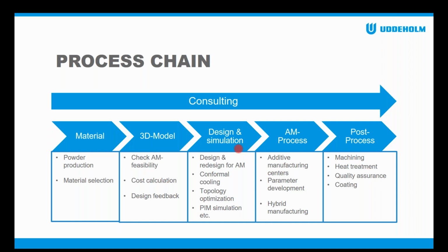Well, often when you turn to additive manufacturing for plastic injection molding, it's because you want to maybe decrease the cycle time or improve the quality of the produced plastic part. And you do that by improving the cooling channels. So you want to have a uniform cooling, even cooling in the tool. And that's where we can support you guys with different simulations or redesign just the cooling channels so you get the right uniform cooling that you need for your tool.